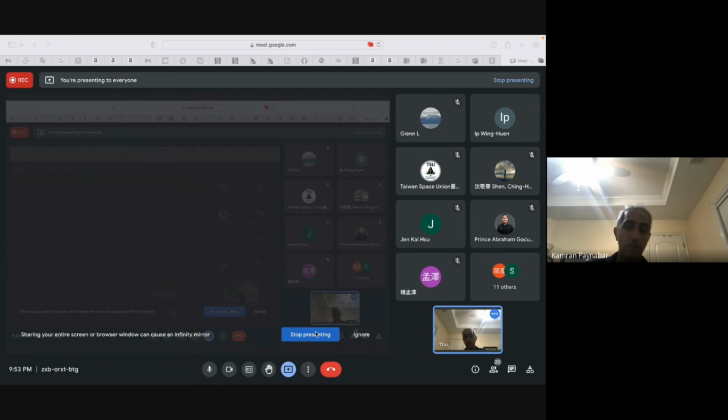any defect or not. And the tests that you are using, either ultrasound or guided wave tests, are point-based tests, meaning that you cannot measure and see the whole specimen at one point. You need to do it point by point. And that would be a time-consuming process if you have a high throughput manufacturing. So what you want to do is make it faster by doing this adaptive sampling. That's one example, after manufacturing of your composite sheet.